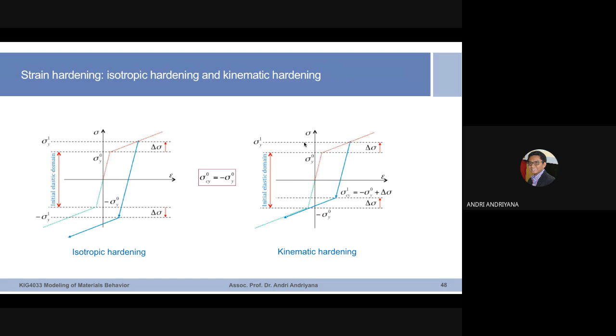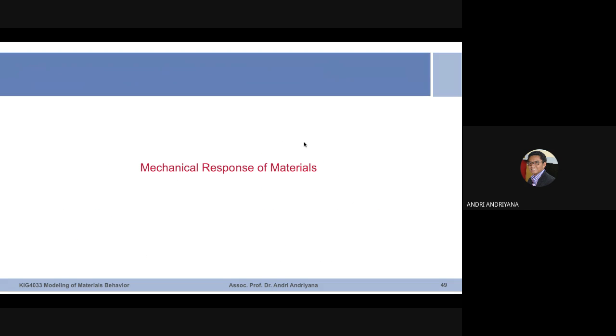So if you look at the tables in the handbooks of certain yield strength of materials, it is the initial yield strength, which is a property. But you can alter it, you can modify it, for instance, by deforming plastically. Okay, this is called strain hardening. Now, these are the things that we have seen last week. Hopefully it is clearer for you now.